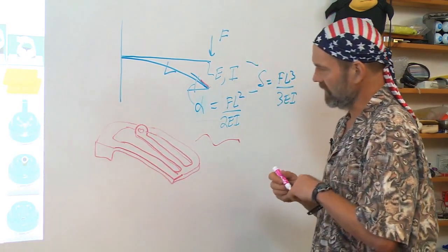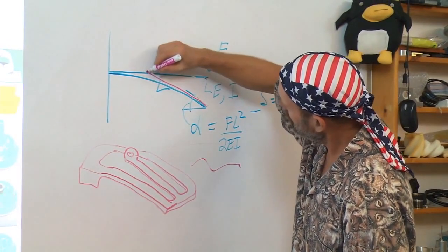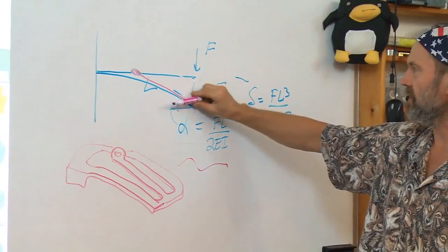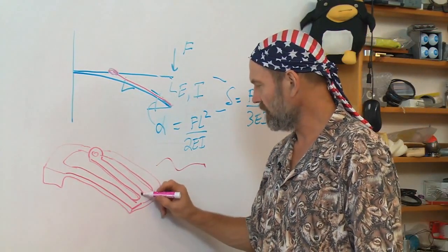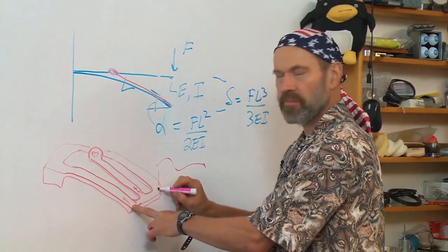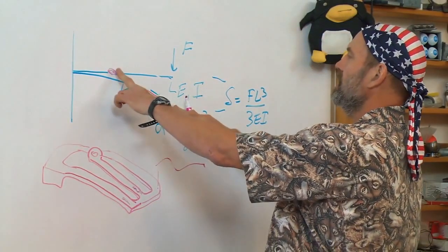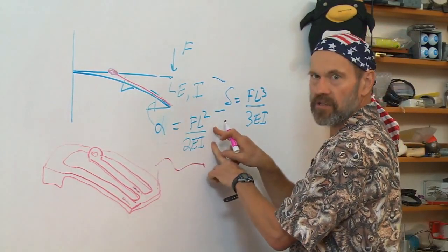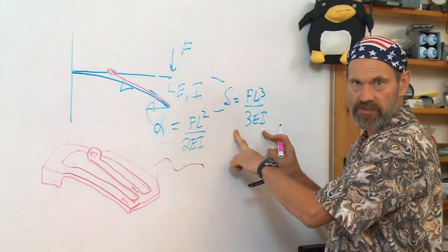Okay, so here's our lens element back here. Remember the principle of the Abbe error, Abbe offset. There's no forces on this middle beam. It is going to have the same slope as the side beams do, which have the forces applied to them, which means that there is some point where I can use this angle times some length to cancel, for this application, what is the parasitic error motion.